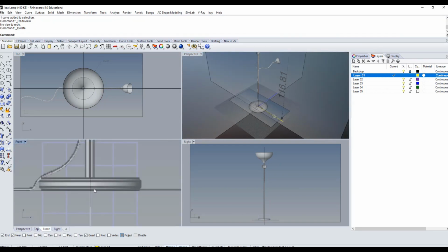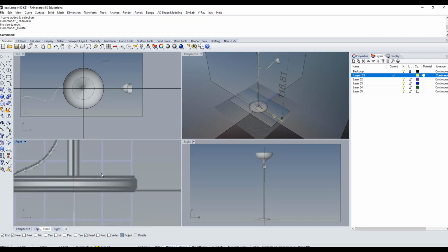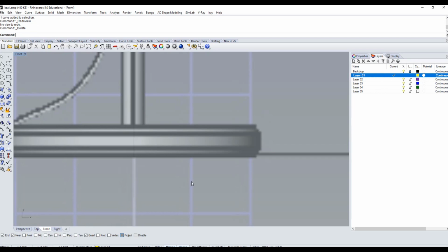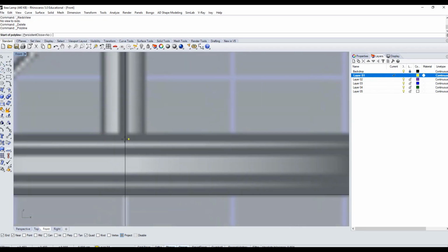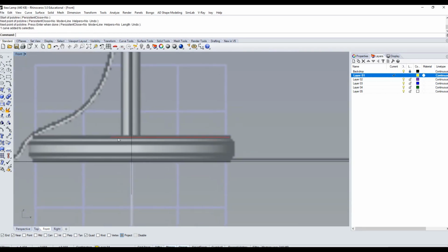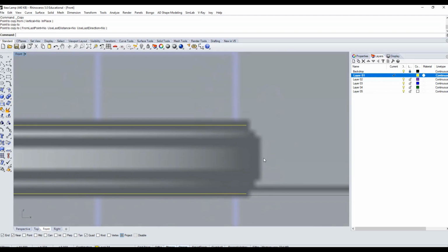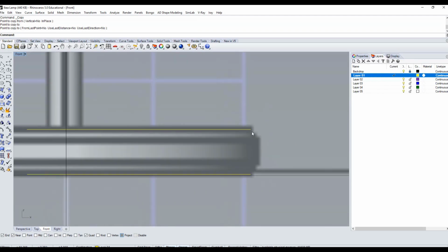Okay, perfect. So what I'm going to do is start working with the base. It's a pretty straightforward shape. I'm going to start drawing, maybe starting at this point here, and press Shift and left click to position this point. I can take this line, make a copy, snap to this endpoint, press Shift, and position it about here, and right click to complete the copy. Okay, now I want to start at the midpoint of these two.